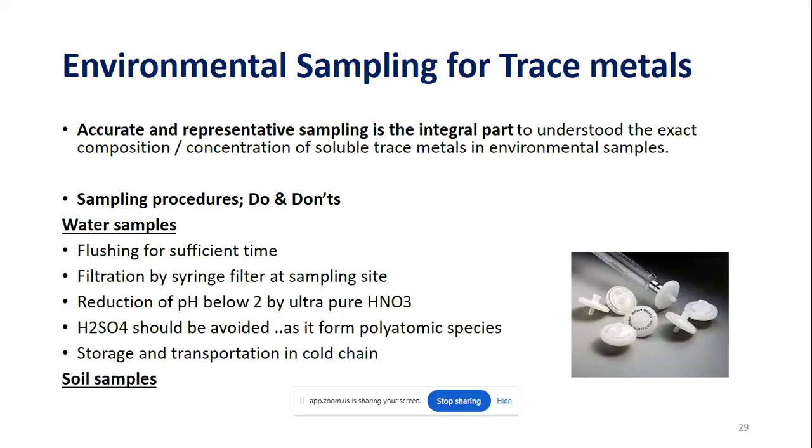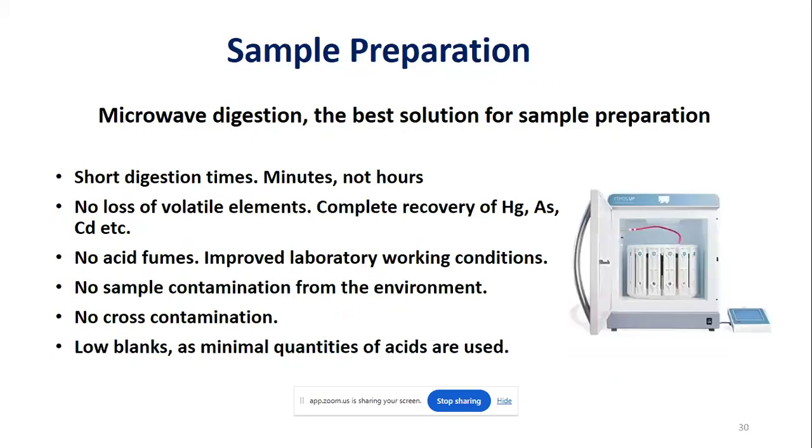What is the use of this syringe? Why we use this syringe and the filtration cap is that the turbidity remaining in the water sample gets removed by the caps or the filter papers. So turbidity is removed in the field itself, and after that we add some ultra pure nitric acid to the sample,